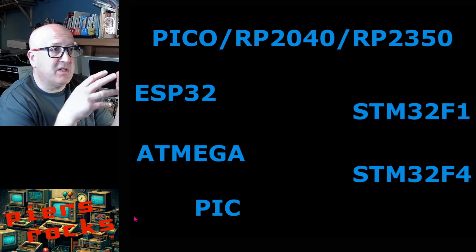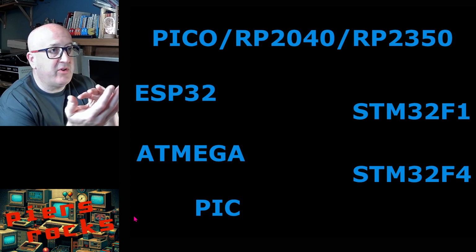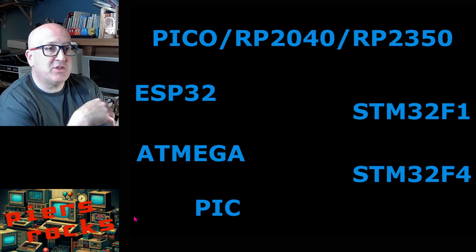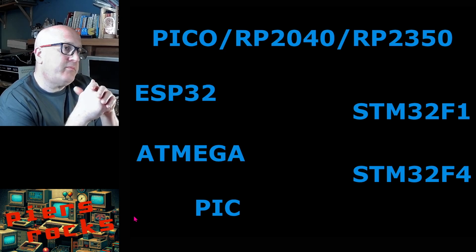That was actually another consideration I had with all the micros. Could they run with an internal oscillator and internal flash? Pico, yes, internal oscillator, no internal flash, except for some of the very new RP2350 variants. The ESP32, you need external flash, or you need quite a large module to use, and so on.